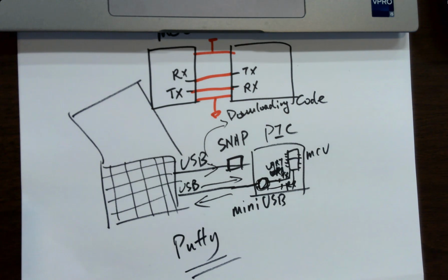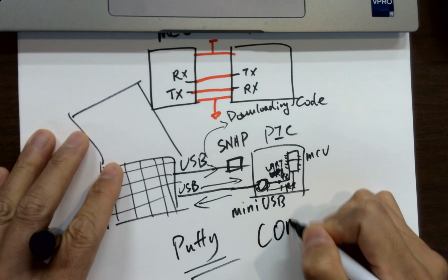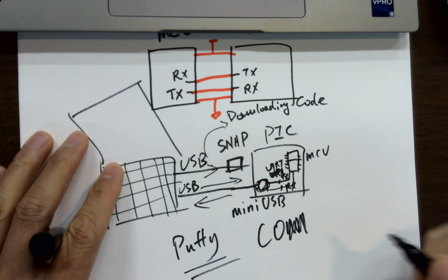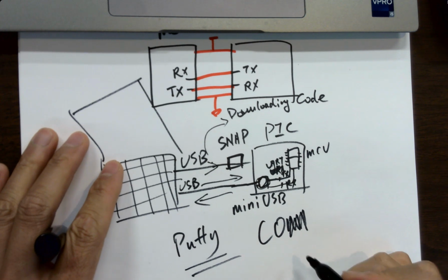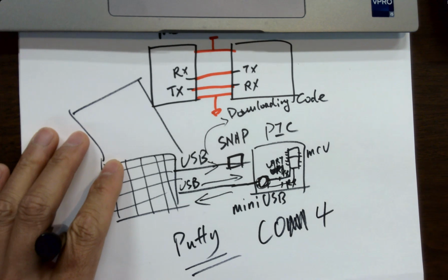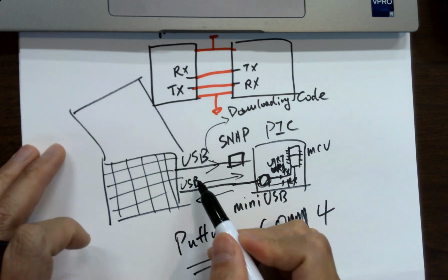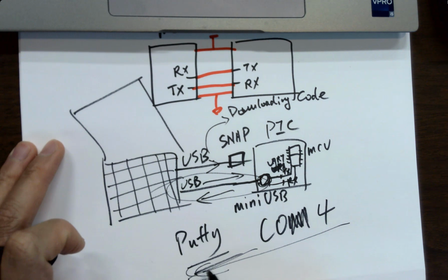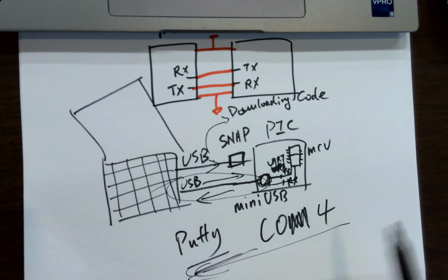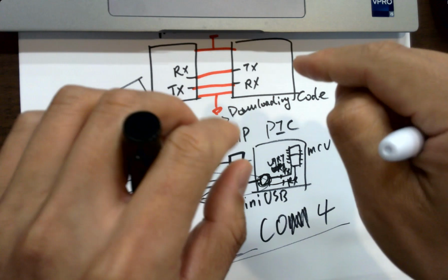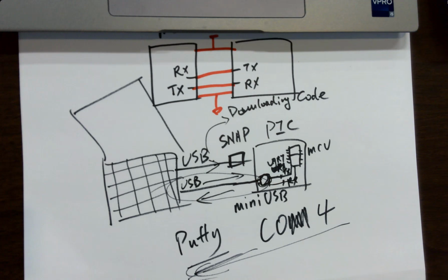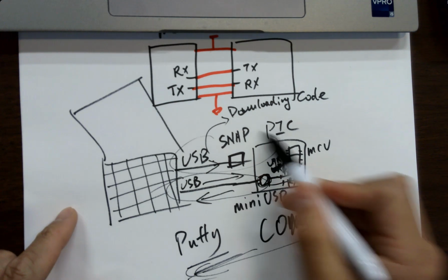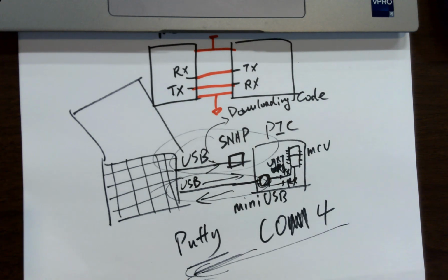There's a little interface, okay? And it's asking you to choose a COM port. Oh, COM port. So that COM port is a UART port. For example, COM4. If you keep this cable connected, you should be able to do all these PuTTY transmissions. I can see data being sent to the PuTTY interface, or you can type something in the interface and send it to the board. You don't need this one. Okay? Right.